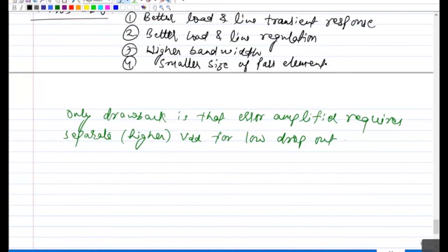So let's say the majority of the total area, 50 to 60% of the total LDO area, will be taken by your pass transistor. And then the second major component will be your compensation capacitor, basically. The compensation capacitor you'll have in both cases, PMOS and NMOS.